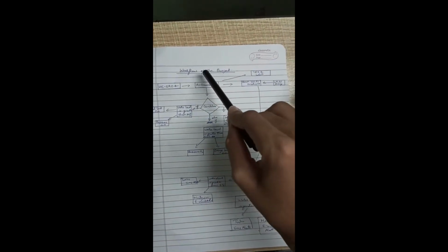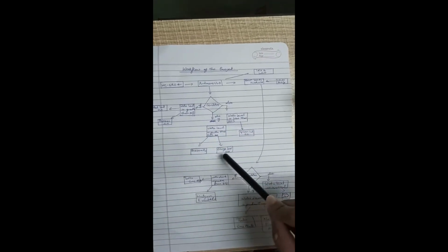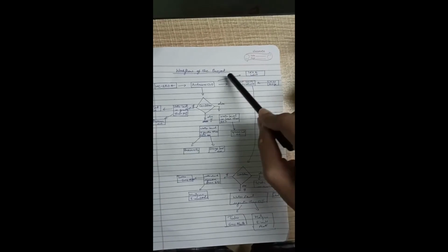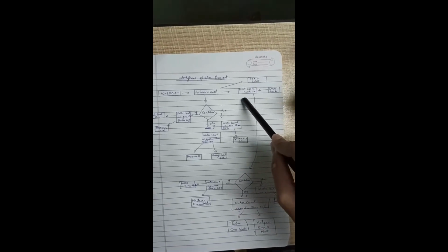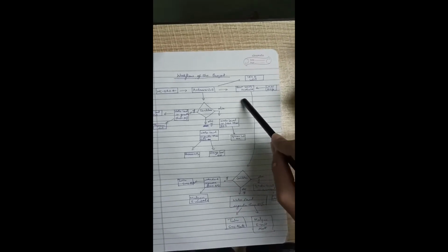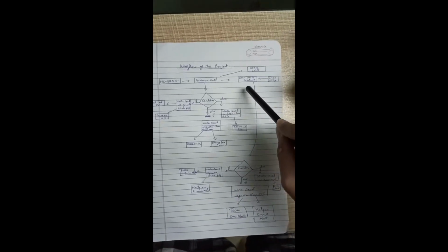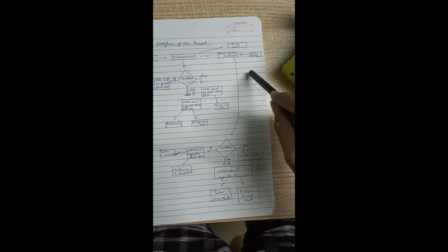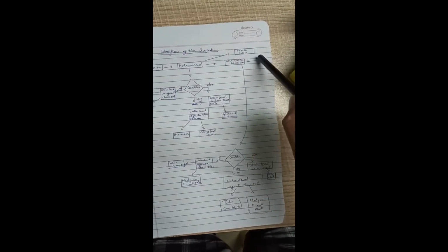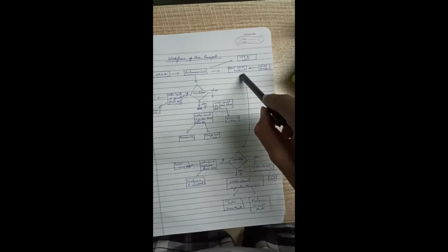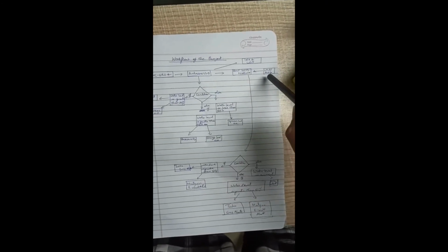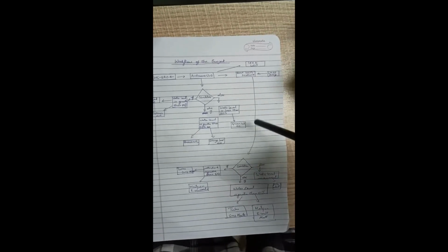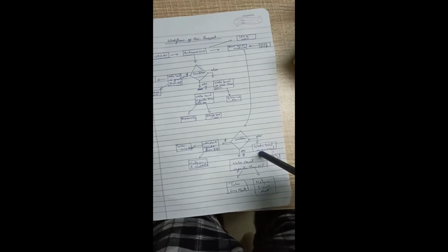Now after the Arduino has done all the conditions like looping and all, the Arduino will use UART communication with the Bolt Wi-Fi module. Now the Bolt Wi-Fi module will take an important step in giving the SMS alerts as well as the email alerts. Now let's look at the conditions. Also, to the Bolt Wi-Fi module, the LM35 temperature sensor is connected. So the LM35 measures the temperature present in the surroundings. Now let's look at the conditions that are present.